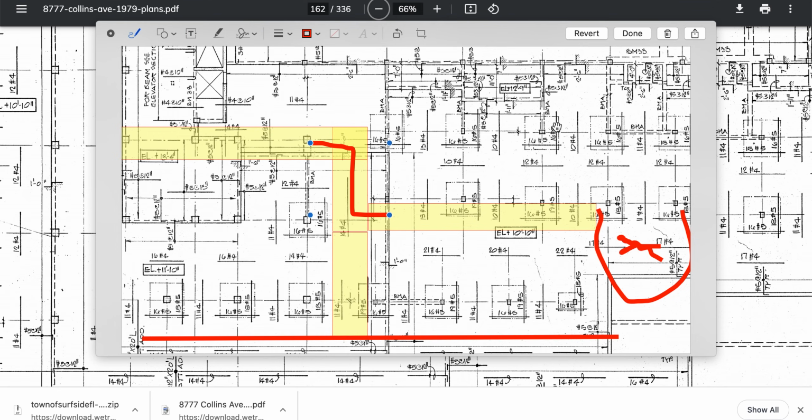That sagging area, if you will, is the tributary area I'm referring to. Now, that tributary area, we don't want it to sag. So what would you do? Well, you would increase your floor thickness, or you'd add some reinforcement inside your floor thickness so it doesn't deflect. And now you can get the greater spans. So that's the tributary area, basically. That's one of the best explanations I can give you of tributary area. And they're between all of these spots. Here to here, here to here, here to here, here to there.